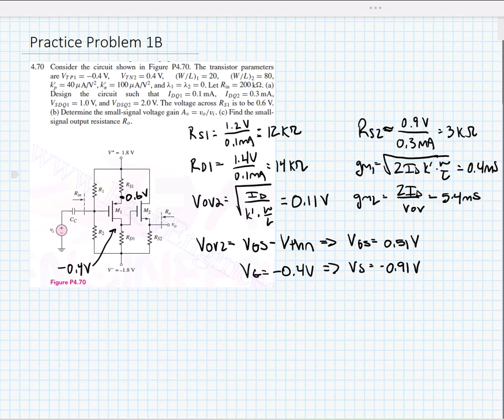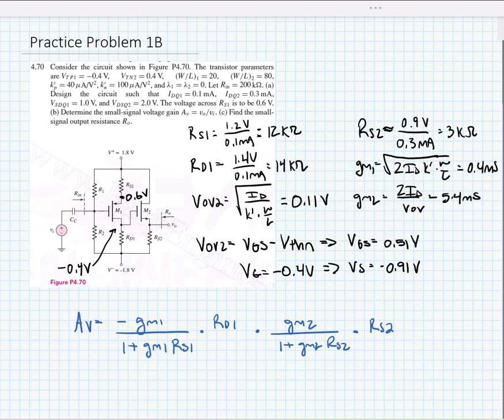So we can now write our voltage gain expression. We don't have any capacitors shorting the source resistances in this particular case like we did in the last example. And we also note again that the lambda values given are equal to 0, which means that the R naught for each of these transistors is equal to infinity, so we can neglect the resistance looking into the drain.